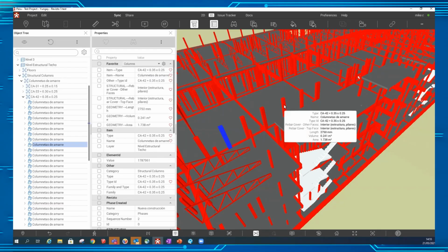So if for instance, there's a contractor's model that has reinforcement quantities embedded in it, that might be something we're interested in. So I could just hover over each of these and take a view on whether I agree with what's in the model or not. So I set up a search there for columns. You could do the same with windows or doors, so that every time you hover over something, you're getting the information that's really important to you. So I think that can be quite useful.